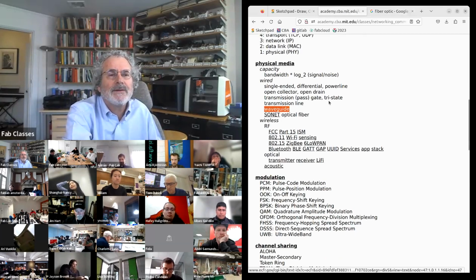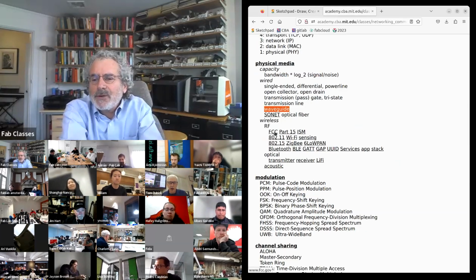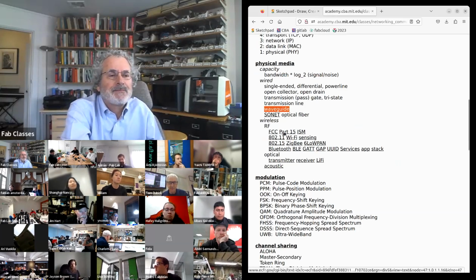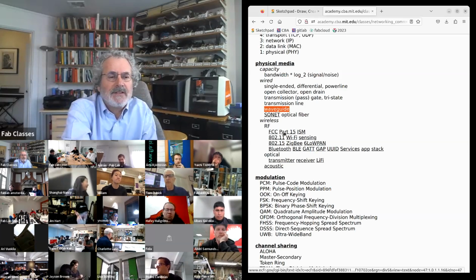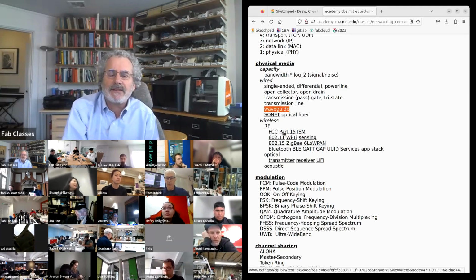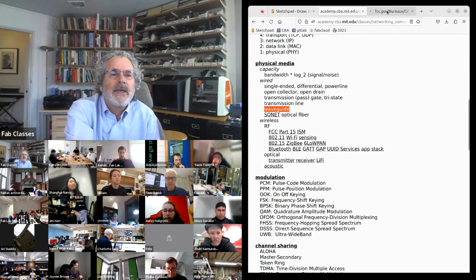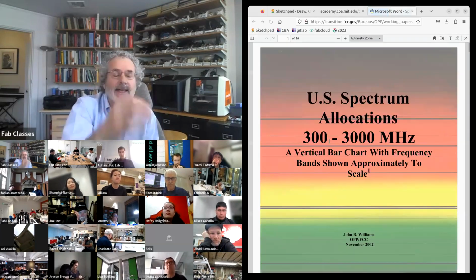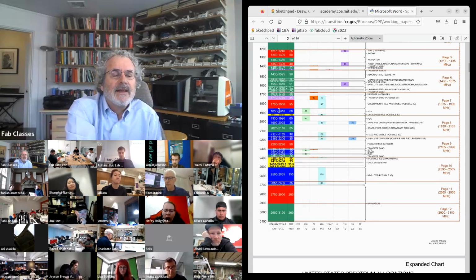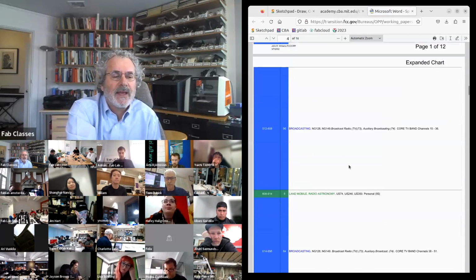So those are wired. For wireless, each country has a body that manages the spectrum. In the US, it's the FCC. Part 15 is the part that has to do with what we want to do, sending radio messages. And what we care about is this part called ISM. So this is frequency, and then this is who owns that part of the frequency.